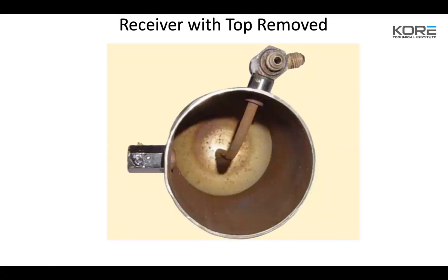So one thing on this style, guys, right here, can you guys see my cursor on the screen? Yep. So right here, there's a soft plug in these receivers. So this is a common leak. Anytime the system goes under an extreme amount of pressure, they're required to have some kind of soft plug or pop-off mechanism in all receivers so you don't create a bomb.